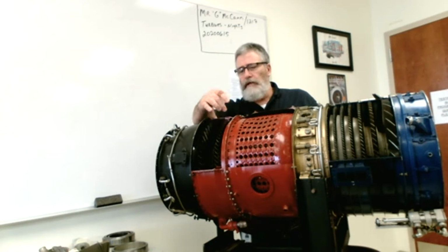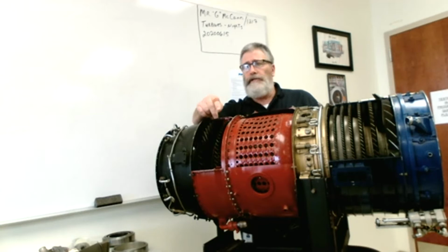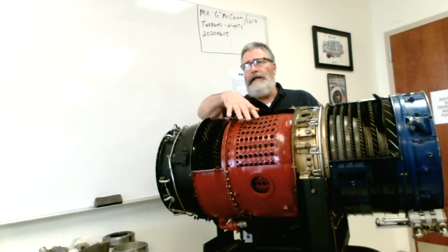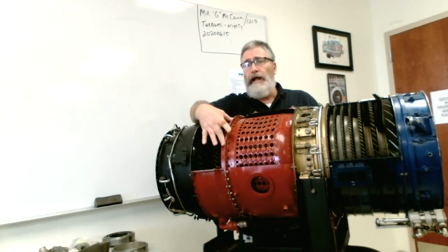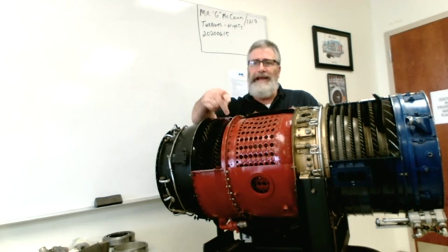And it's the hottest point in the engine, so it's also referred to as the critical location in the engine, because temperatures back here can range extremely high, let's say 1700, 1800 degrees Celsius, right? So if we were to exceed that temperature, then we would damage this nozzle. Everything is built around the heat capability of this first stage nozzle. Okay, that's very important. This is the actual highest temperature point in the engine.